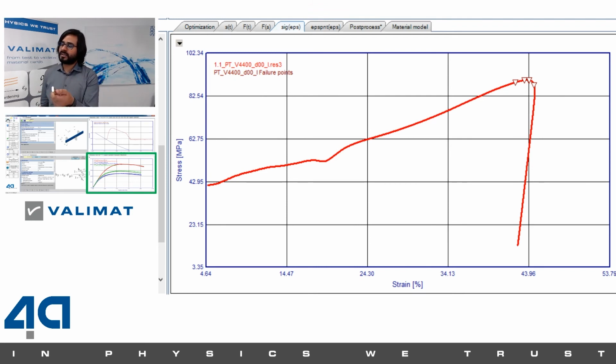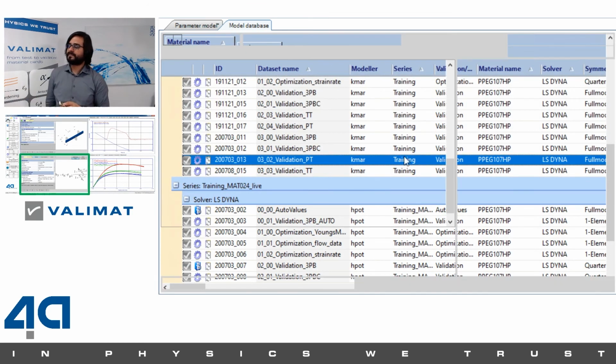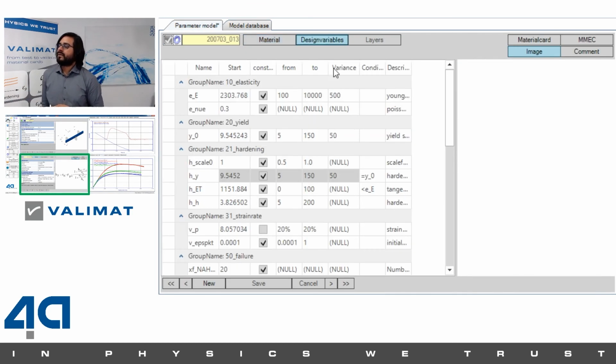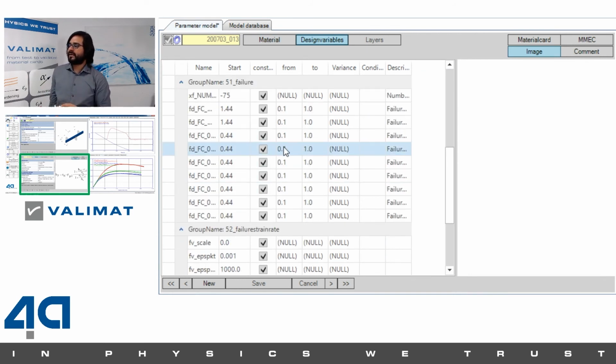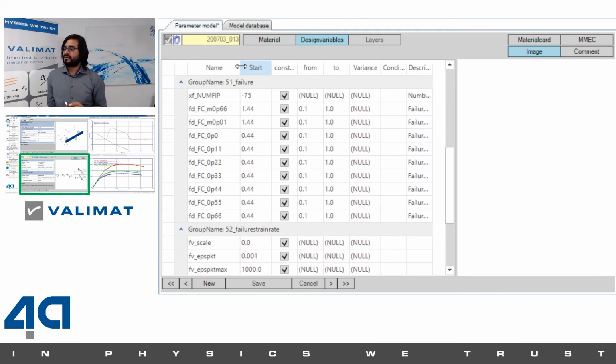That is what is in the failure model that I've set up here. An average of all these strains is given in the table here. The first two values are our compression side; we set them to a really high value so that we don't have failure. And then we have this averaged plastic strain value.